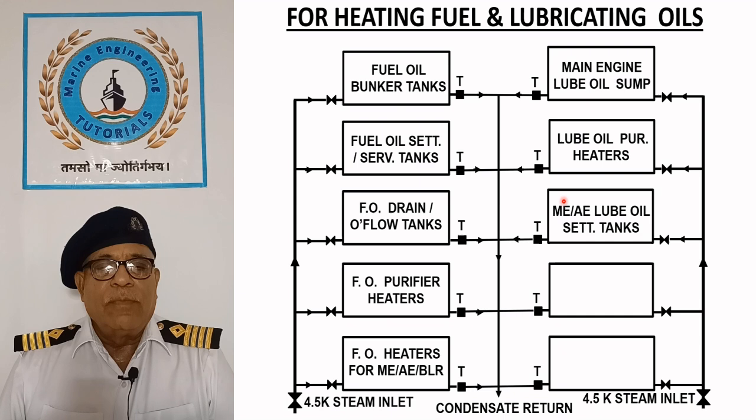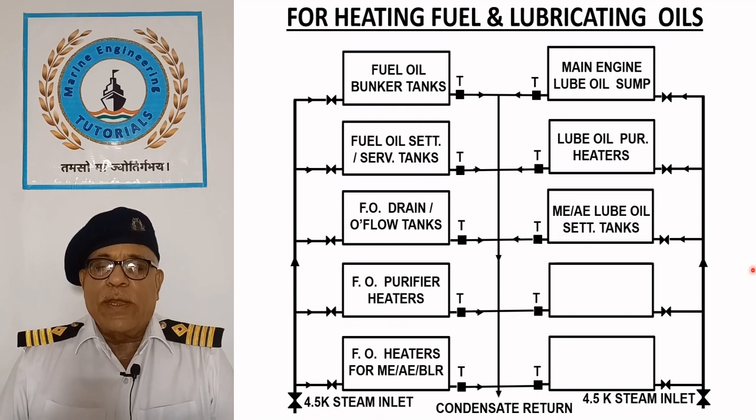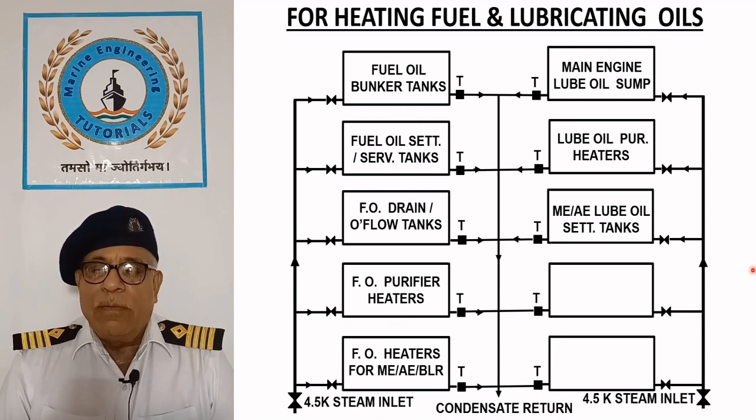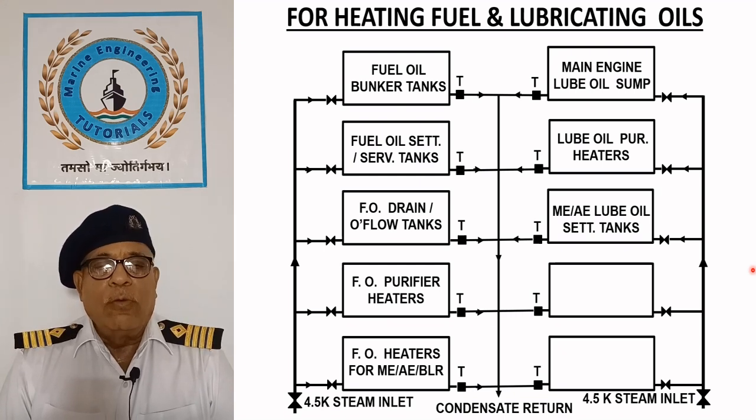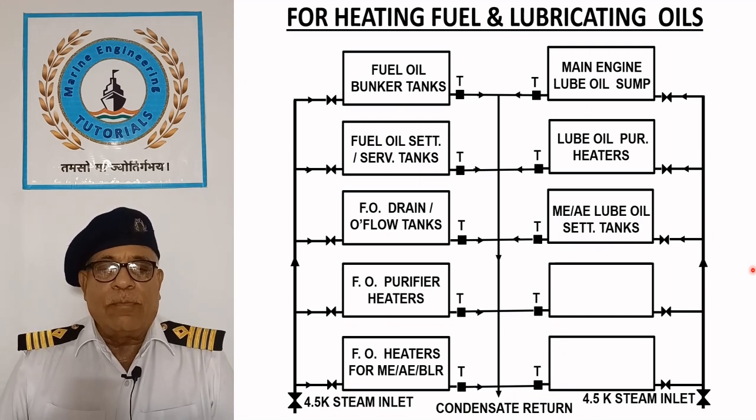Main engine and auxiliary engine lubricating oil settling tanks. If the lubricating oil in the main or auxiliary engine is heavily contaminated with water, it is transferred to the respective settling tank and heated to around 70 degrees Celsius to allow water to settle before batch purification.